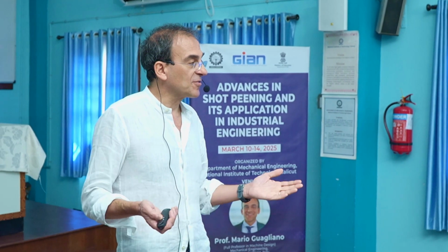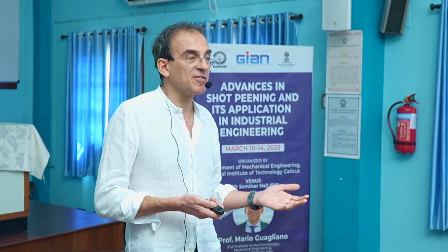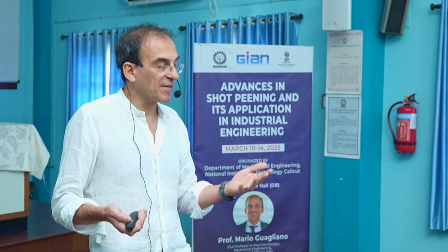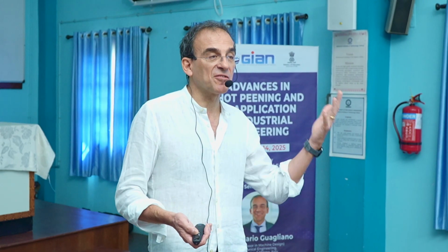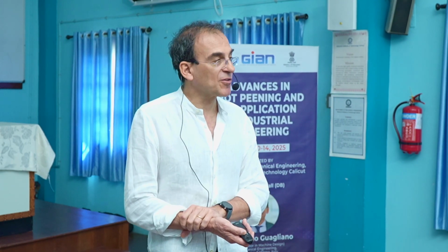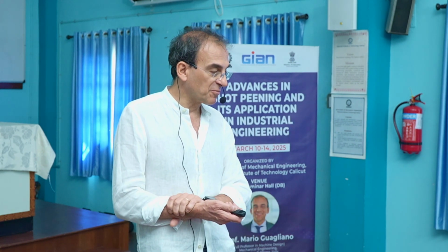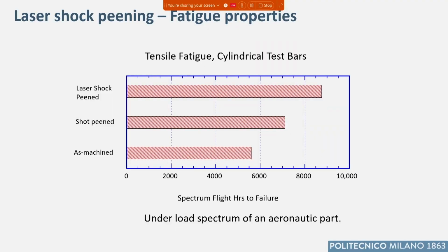Okay, and is it worth using laser peening? It depends on the application. Maybe if the increment is just 20 megapascal, shot peening can be enough, but if it's larger, laser shot peening could be preferred.